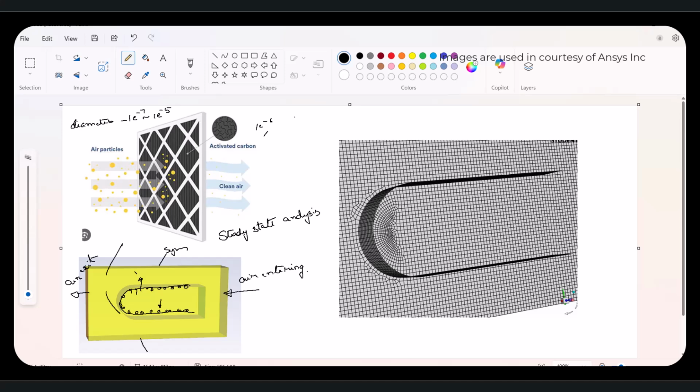So we will split it into two parts. In part 1, we will see the UDF and everything for the particle trapping when the diameter is greater than 1e-6. In part 2, we will also include the trapped particle mass and how it affects the porosity. Initially this is a plain domain, but as more and more particles get deposited, it is not a free air domain anymore. It will be a porous domain with a larger number of particles, and it will create some resistance to airflow. That would be simulated in part 2. So we will take this as part 1,